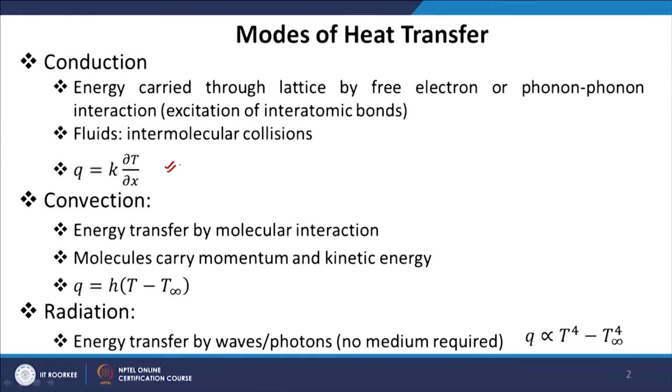But again, convective heat transfer is also a local effect. Also, in conduction the heat flux is proportional to the gradient of temperature, which is a linear dependence on temperature, and in convective heat transfer also the heat flux is a linear function of the temperature of the fluid. On the other hand, radiation is not a local phenomenon.